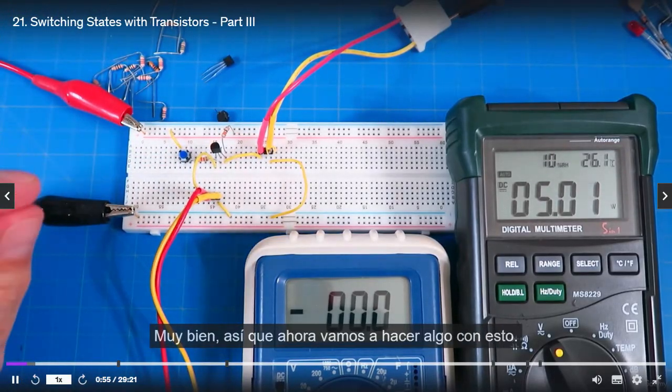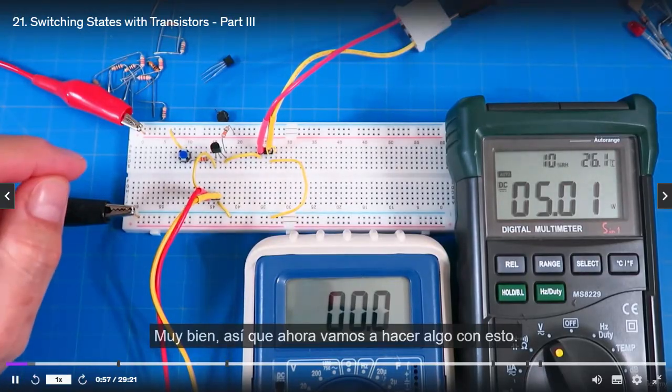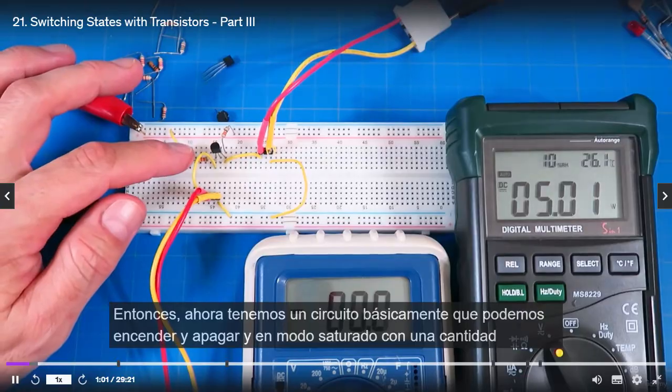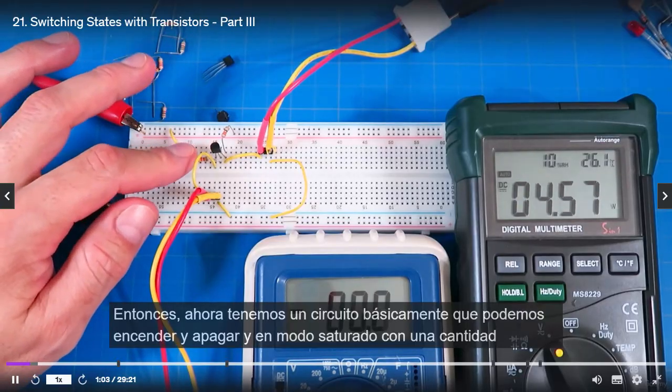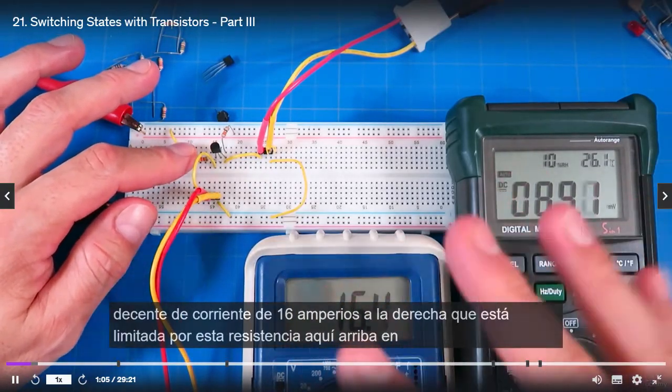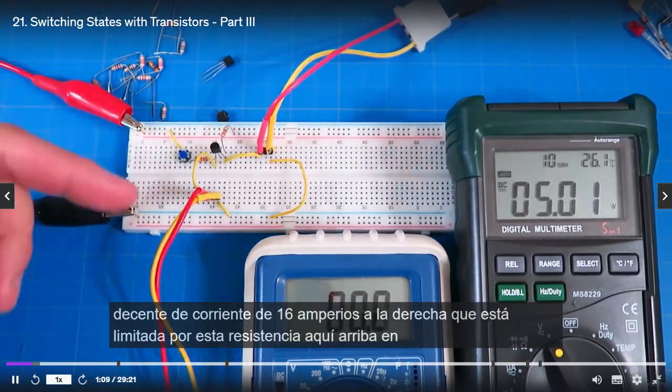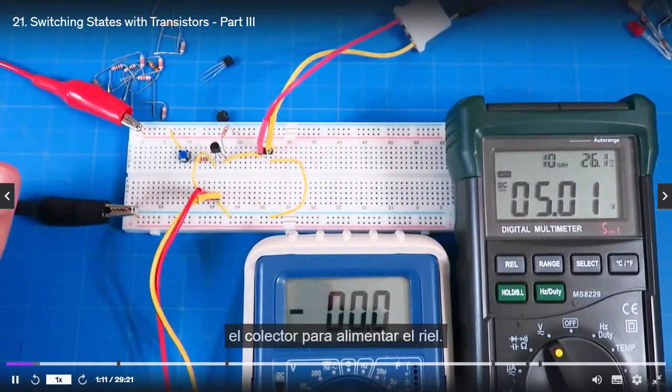Now let's go ahead and do something with this. We've basically got a circuit that we can turn on and off in saturated mode with a decent amount of current, 16 milliamps, which is being limited by this resistor up here in the collector to a power rail.